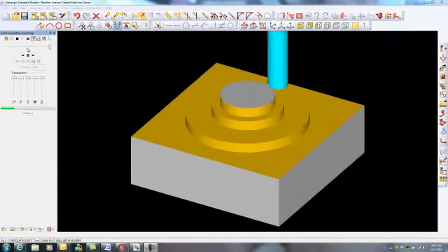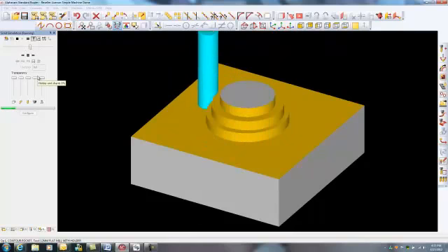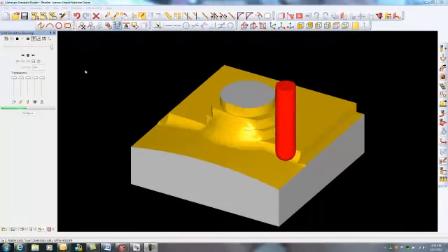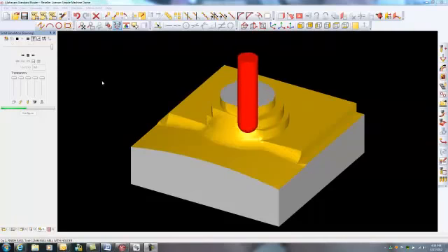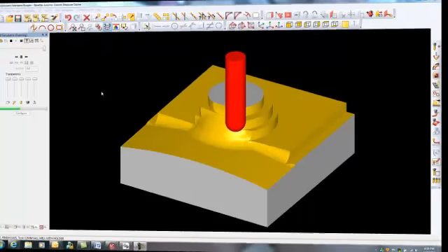Simple toolpath can be applied to any surface. You can program rough cuts as shown here, and then simply apply finish cuts in parallel motion. This can be applied to any number of surfaces, giving you full capability to create surfaced parts in a 3-axis mode.